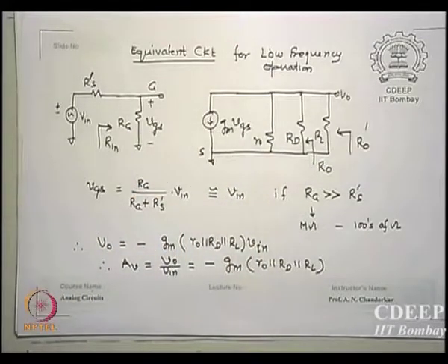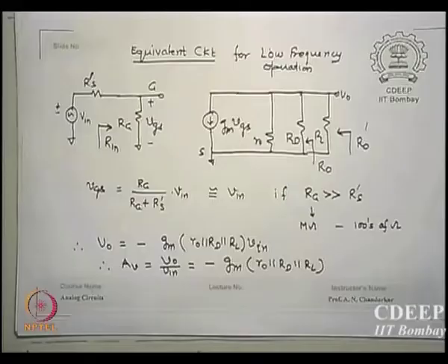Now we also need to find, apart from gains, two more parameters. What is the problem I said in connecting the two circuits in bipolar? The output impedance and the input impedance are sometimes equal or bad, one is much lower than the other, so it is called loading effect. Now I want to see how much is the R in and how much is the R out of my circuit, so that I can cascade. What do you mean by cascade? The output of the first stage is given to the input of the next stage, is that correct? This is called cascade. So can I cascade? Another word which I am going to do after this is cascode. What could it be different from?